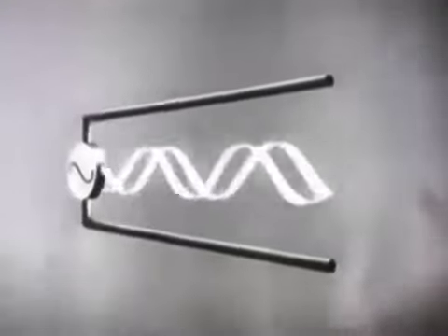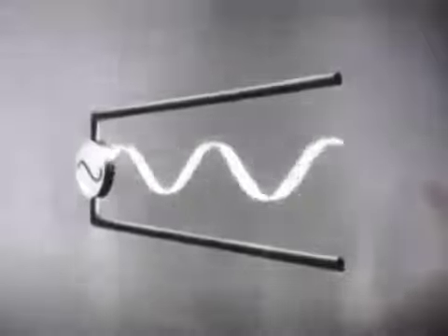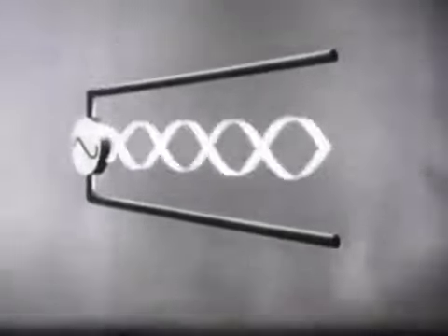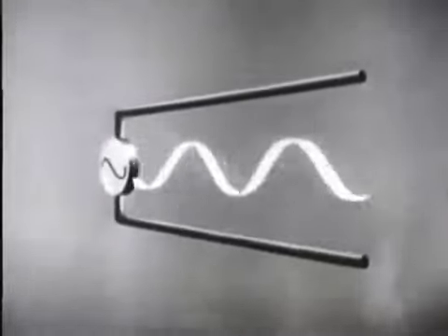An open-ended line achieves the same result. The open end of the circuit offers maximum resistance to the passage of current. There is no power dissipation. The incident wave simply bounces back at the end of the line to become a reflected wave of maximum amplitude.